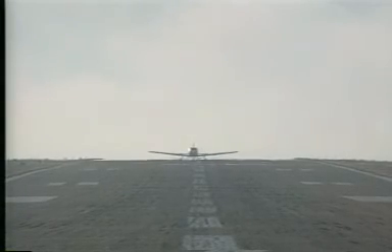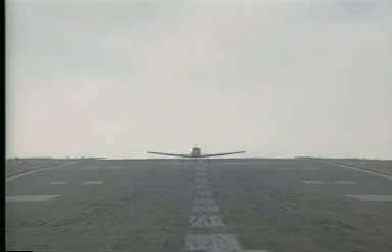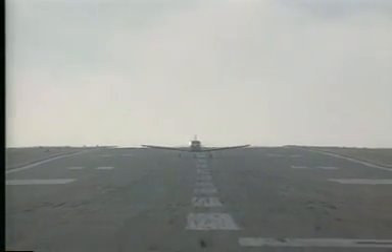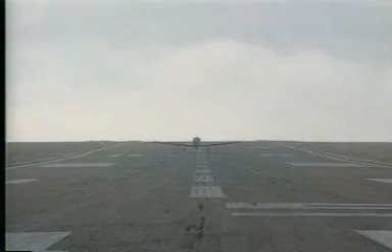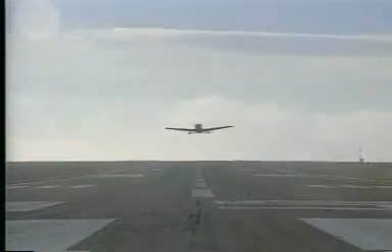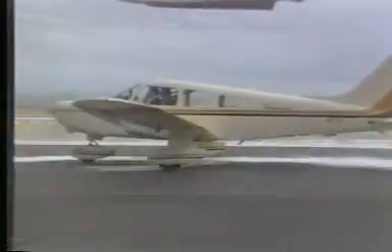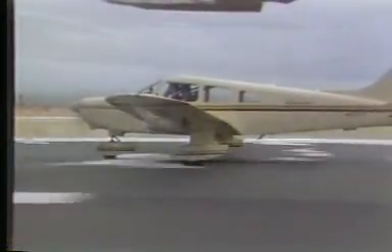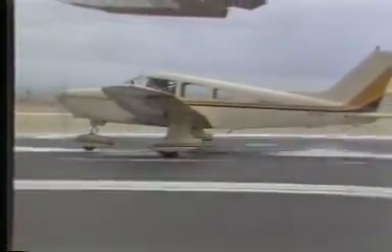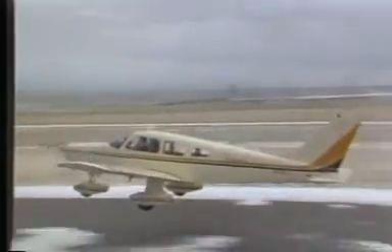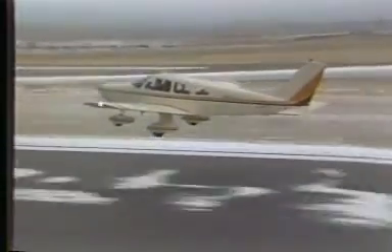The opposite conditions exist when the runway slopes down. Now your takeoff roll will decrease because you're able to accelerate faster. However, your landing roll will increase because it takes longer to slow down. You should also pay close attention to the effects of operating on runways with surfaces of snow, mud, water, or grass. The friction produced by these surfaces may significantly increase your takeoff roll.